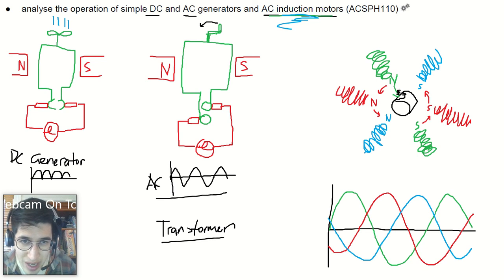Remember, this south pole is appearing as this north here is disappearing, and this one is appearing now. Stay with me. This is the important part. The south pole is now attracted to the second north pole in the red. Okay, so this starts to spin. South's attracted to the north there.